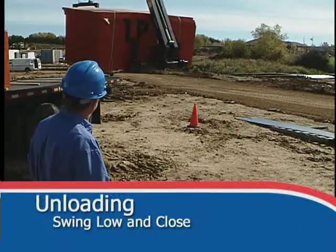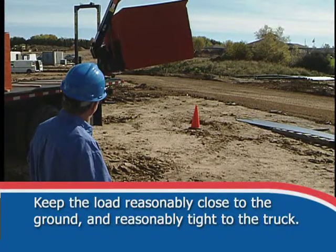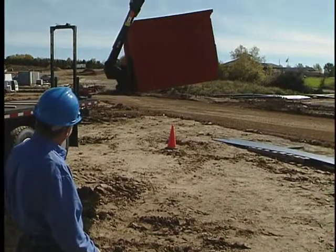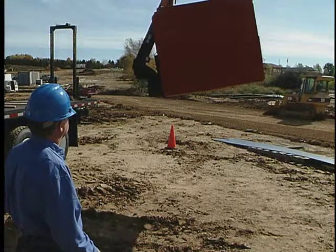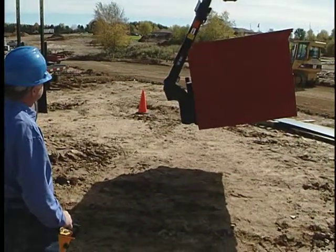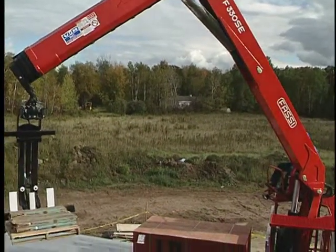The rule of this rotation move is swing low and close. In other words, keep the load reasonably close to the ground and reasonably tight to the truck. There is no need to extend loads out further or higher than necessary. Swing low and close. This will keep the load more manageable and makes it a speedier trip to the ground in event of trouble. Even for high lifts, keep the load low until the crane is angled correctly.